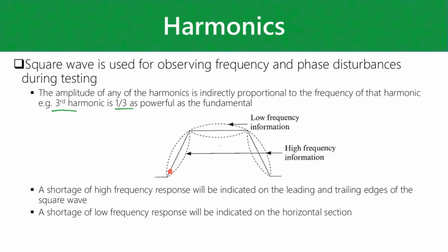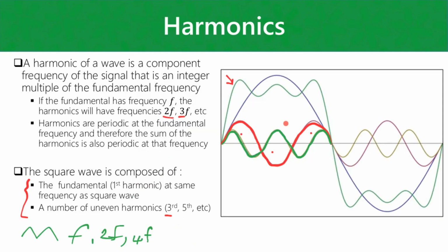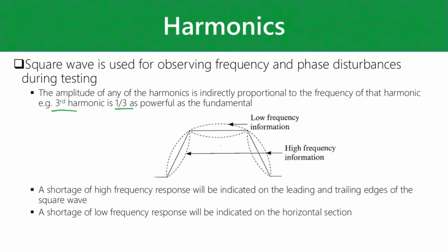So essentially, if you take a square wave, what's happening is you are playing around now with the harmonics here. So you're either filtering them out or introducing extra harmonics into the system. Maybe some of them phase shifted. But anyways, if you, for instance, get distortion on the slopes of your square wave. So remember, your square wave is not perfectly square. It is somewhat sloped on the edges.